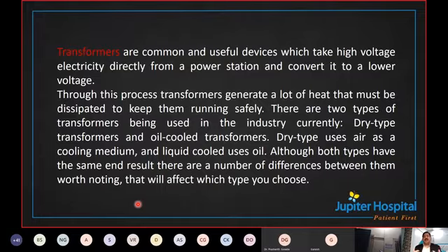So you do not have any option. So most times, at least in Mumbai, because plot size is a difficult problem, every time the dry type transformer has been taken, because the advantage is that we can put it inside the basement area. And cost wise, dry type is costlier. If you see a 2 MVA transformer, it costs maybe 20 to 24 lakhs.